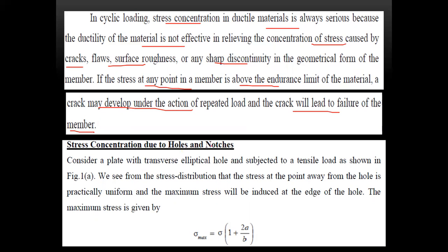Got it? Next, stress concentration due to notches and holes. Consider a plate with a transverse elliptical hole subject to a tensile load. We see from the stress distribution that the stress at a point away from the hole is practically uniform, and the maximum stress will be induced at the edge of the hole.